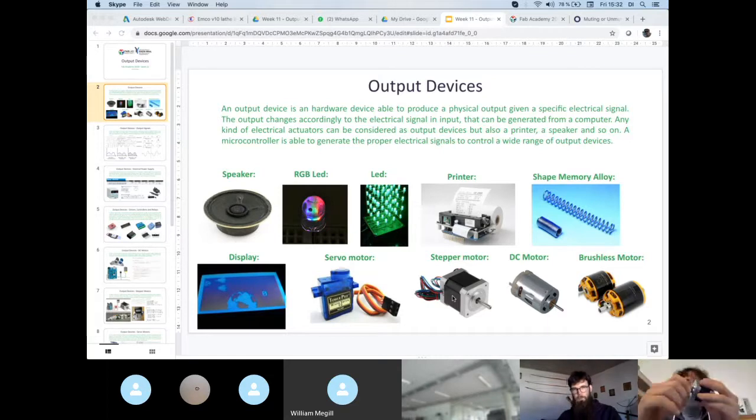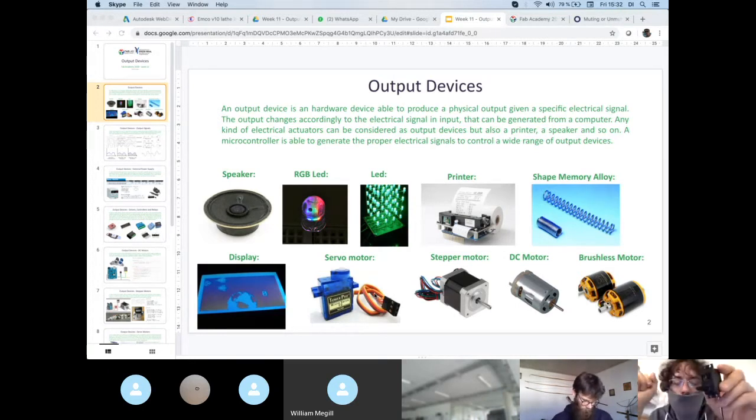And so one of the main differences between a stepper motor and a servo motor is that the servo motor, coming in this small shape that you see here on the screen, or like this one that you see here in the camera, can rotate a specific amount of degrees. Usually the small ones that you can buy will rotate by a maximum of 180 degrees. So you have this limitation, like from here to here, for example.